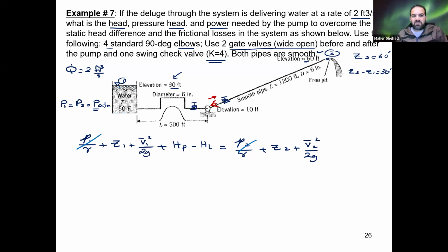What did we say about the tank? We said any tank with respect to the flow inside the pipes, the velocity. When we compare the two velocities, this one is too slow, so we can't see it really moving. I mean, or it can be neglected, especially when you say V square. And if you look at point 2 this time, that's the velocity of the flow inside the pipe.